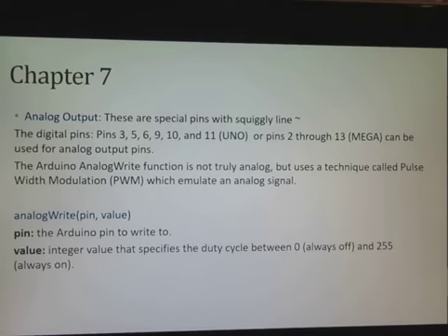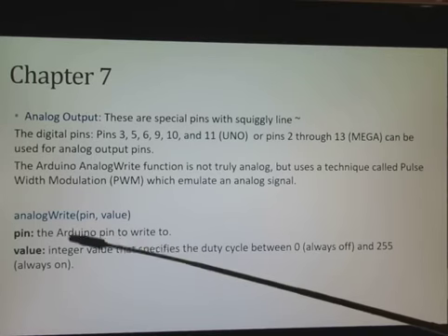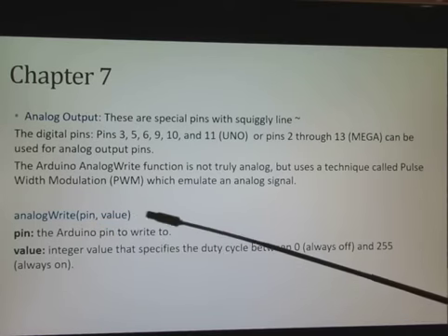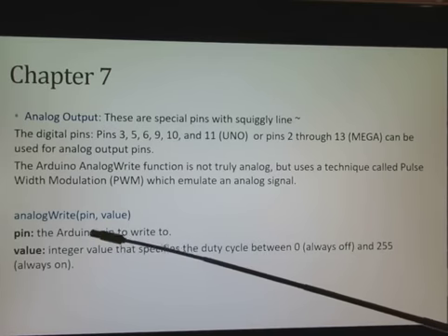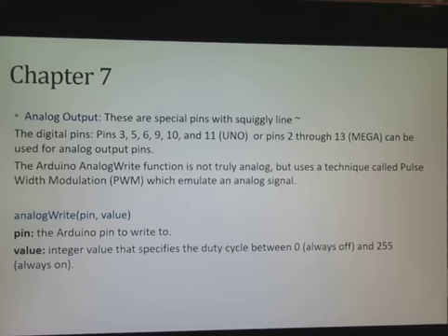And really the analogWrite is not really a true analog signal. But make sure you understand the syntax for analogWrite. We don't have to set it as an output like we do with digitalWrite, but we have to specify the pin and the value. And that value is going to be a number between 0, which is always off, and 255, which is always on.